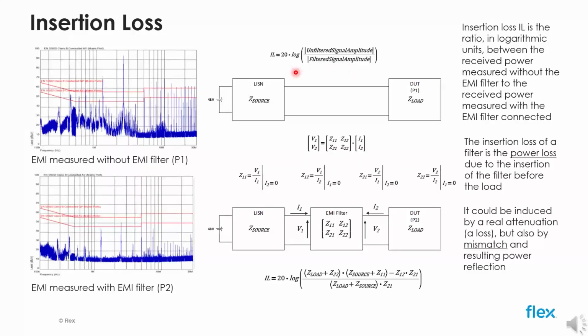It can be conveniently expressed in terms of impedance matrices, as you can see here, and that is because the terminal impedances can be directly measured. Otherwise, you can use S parameters taken with a network analyzer. Conversion from one matrix type to another is very common, and as we will see, using ABCD parameters is very convenient in the design process.